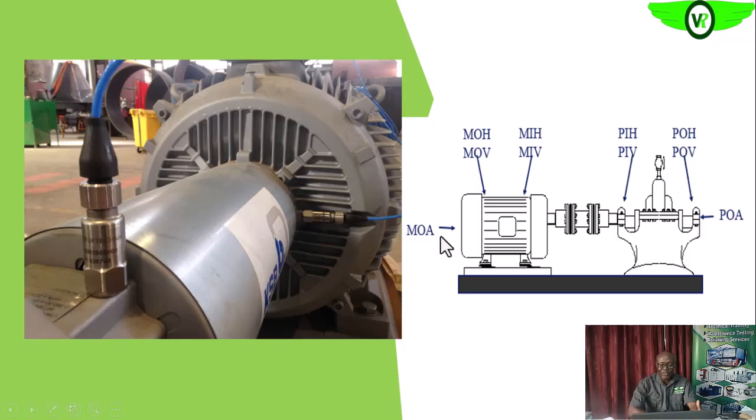So we take vibration reading on each of these bearing housing in 3 axes, okay. We take on the axial axis, that is the axis that is parallel to the shaft axis, okay, or the axis of operation, the turning axis of the bearing that we are looking at. So any direction that is parallel to it becomes the axial direction. Okay, so like in this inboard end of this motor, we know the bearing is here. So since the coupling is here, we cannot really access the axial direction directly.